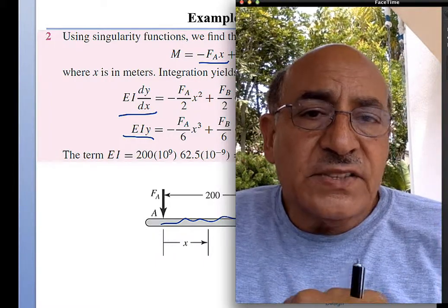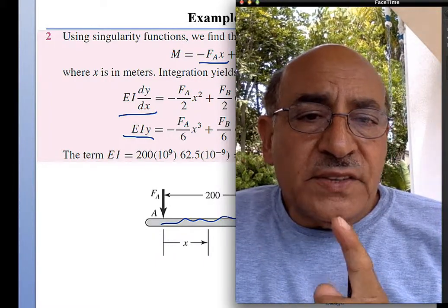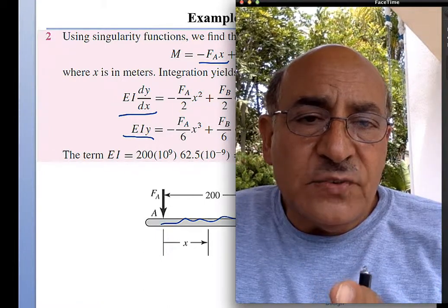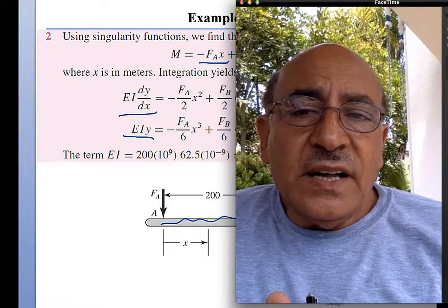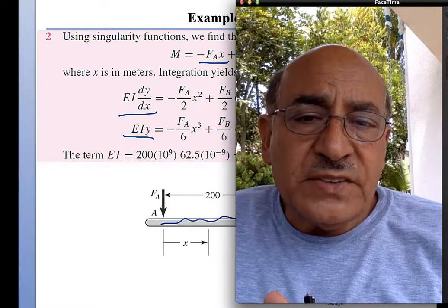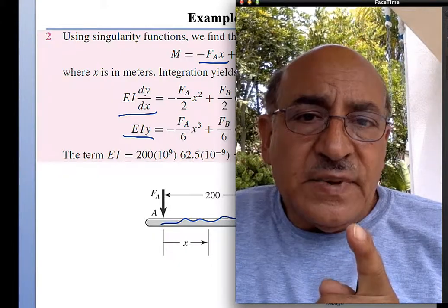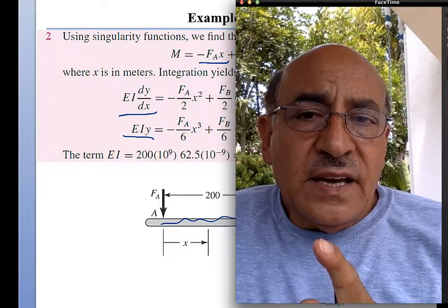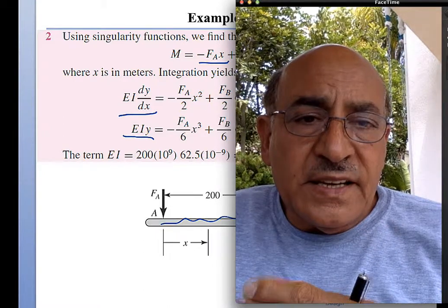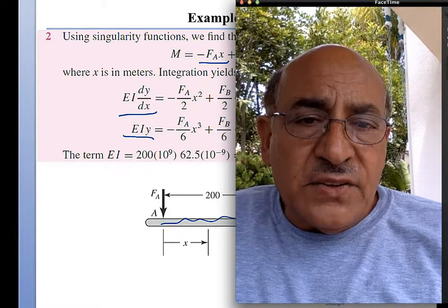And the 3 from deflection are the boundary conditions that we have to find, because now we're not using Castigliano, by the way, we're just using the straight deflection equation from the differential equation. So I have to set the boundary conditions at A, B, and C in the deflection equation, and that gives me the 3 equations I need.